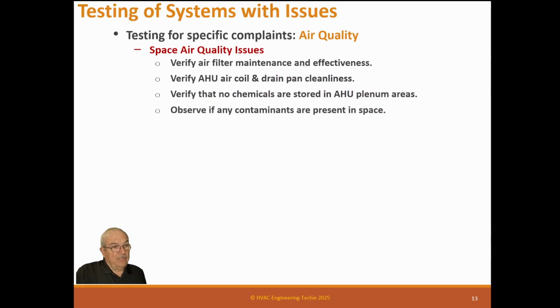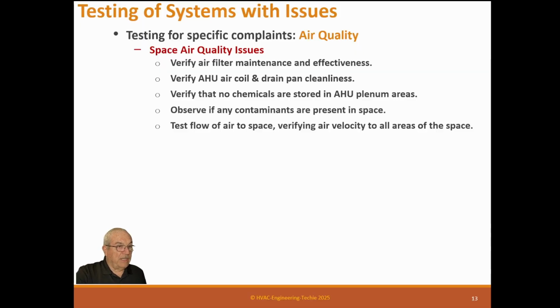Or you could see Legionella if there's water anywhere inside the space. It could be Legionella on the showers or on the faucet fixtures. So that you can look into that kind of stuff. Test flow of air in the space, verify air velocity of all areas in the space. This is also important, that we have air movement and that we're exchanging enough air to clean the air. Test the total building for building pressure.